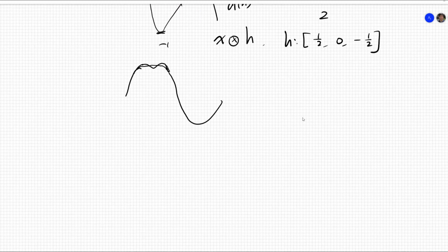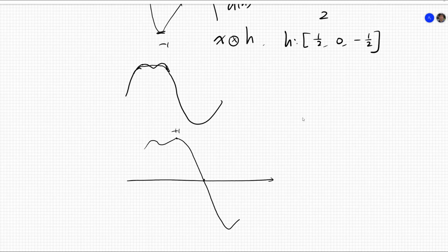The zero-crossing timing error detector is catching the feature that those symbols will cross 0 at the middle point if I'm changing from a positive 1 to a negative 1. If I change from a negative 1 to a positive 1, I will also have this zero crossing point. Ideally, those zero crossing points should be the middle point of my perfect sample positions.